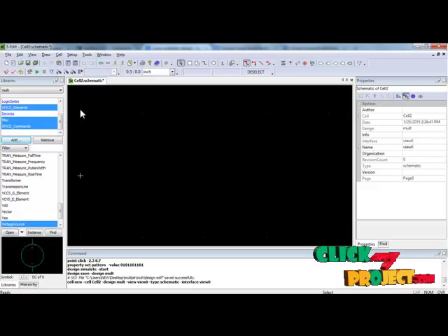So we can design the circuit based on CMOS transistors by using SEdit. Before we start the simulation, we have to select a new cell. Here is the cell menu. Here we have to select the cell menu and select new cell. There you can select a number of cells like cell 0, cell 1, up to cell n. Each cell should contain a different CMOS design. The next process is to set up the simulation. Pressing this icon will lead you to setup simulation. In the setup simulation, you have to set up the maximum time duration for the design, in nanoseconds.